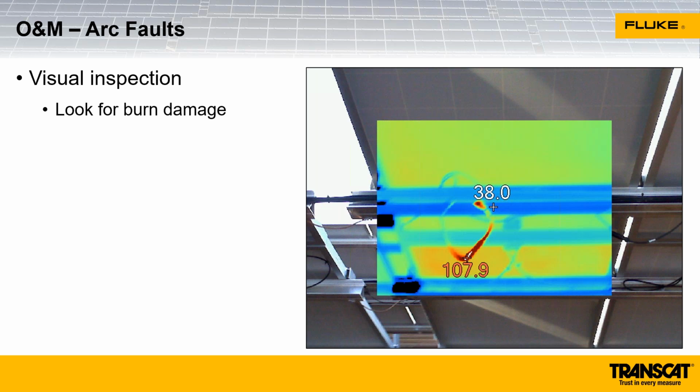A lot of times, those high resistance arcing connections in a connector aren't easy to see visually, so we need that thermal imaging camera. And what we're looking for here is comparing the temperature between different connections. So we're looking for anomalies there, not necessarily a certain temperature actual number. We're looking for differences in temperatures between connections.